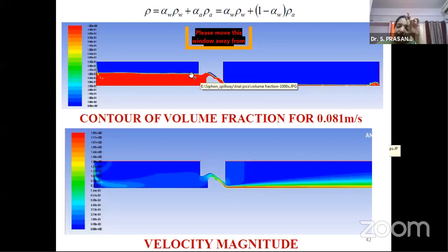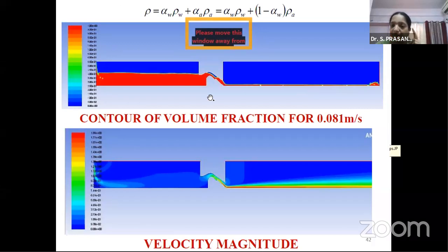So as we are running in between 0 and 1, whatever your interest area is, suppose let us say I wanted to know the volume fractions in between 65 to 70%. That means 0.65 to 0.7. If you initialize this range of volume fraction values, you will get all the values which are there in the complete domain in between those. Because you can also see there is a legend over here which starts with 0 and 1. And there are values which will fall between 0.6 and 0.7 or 0.65 or 0.7.